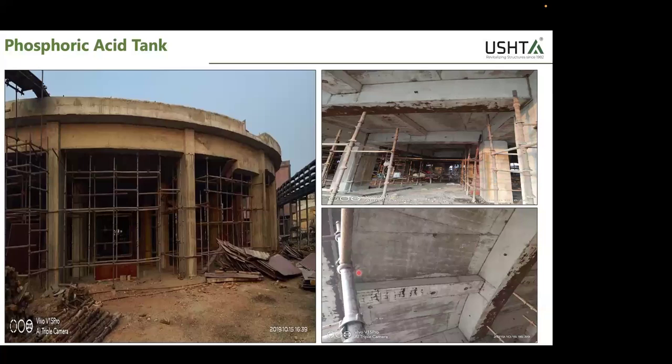So in this case also, when they did the UPV, they found the results were excellent, so they thought it was good. But when they started erecting the tank, during pegging, one of the pegs went inside, and that is when they realized that there are voids in the concrete. And they came to us, they said, we are getting good results, but how is it that these voids are there? So then we did tomography.